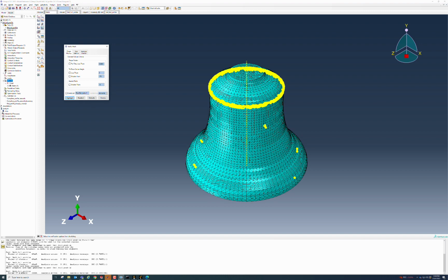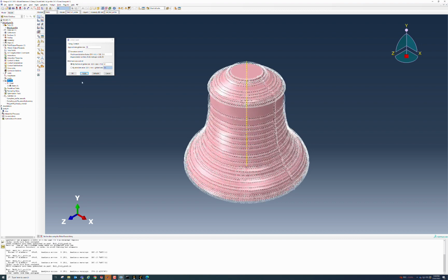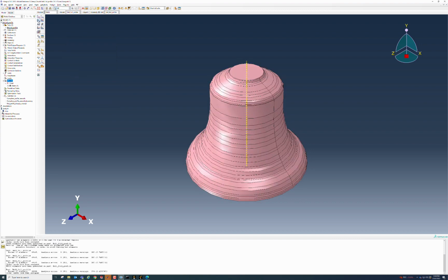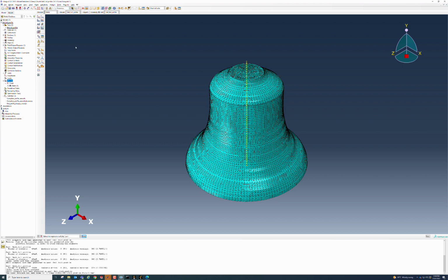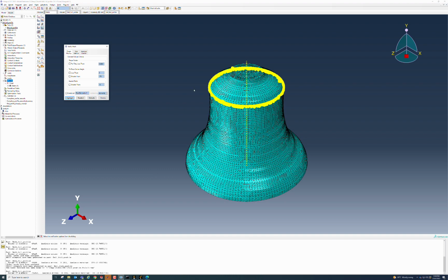of the steps. The step around that crown, around the shoulder area there, is what's causing the issues with the mesh that we're being warned about. And you can see that in a moment here around that shoulder area. So there are some features to help us diagnose the nature of the mesh. We can change the errors and warnings appropriately.